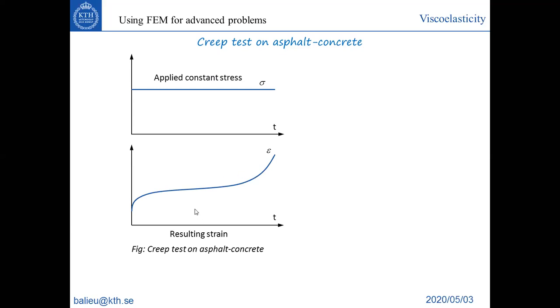Now this is a creep test performed on asphalt concrete. For this kind of time-dependent material, you have this kind of behavior. You have a first part with a very strong increase, and after that a second part where the increase is a lot slower, and after that again an increase of the strain as a function of time.